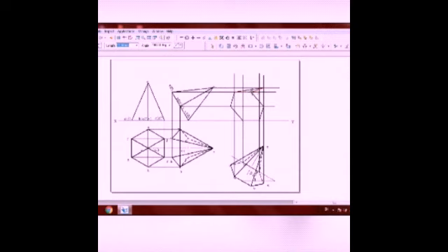Remember, it is a hexagonal pyramid and therefore there must be 6 lines. One important thing is these 3 lines are visible lines, and this line, the next line and the next line are hidden lines. The hint is from the previous front view. With some thinking and imagination, you can decide these hidden lines in the final front view. Make those 3 hidden lines dotted. Remember, in drawing, accuracy is very important, and once you zoom in, if you find some inaccuracies, correct them.